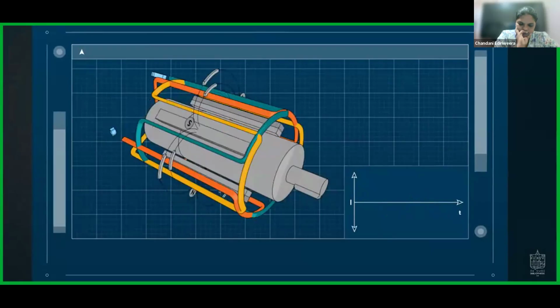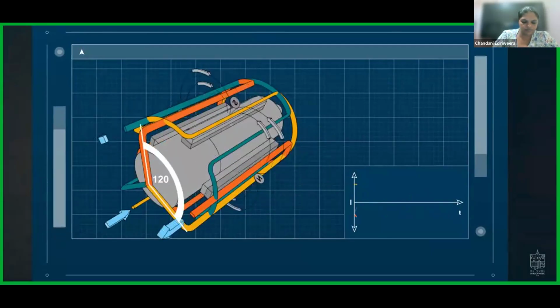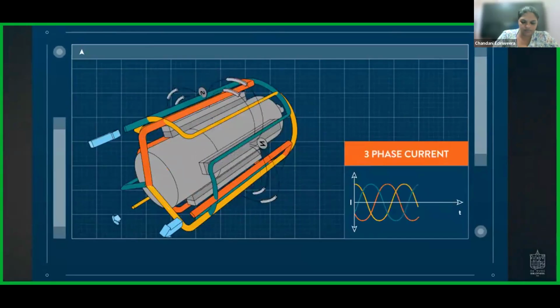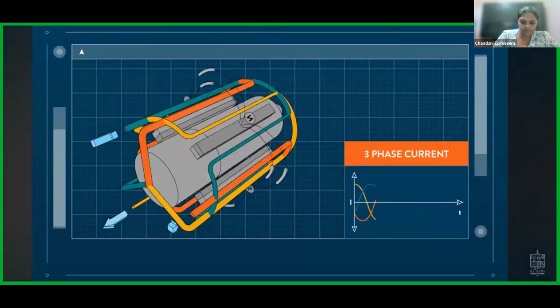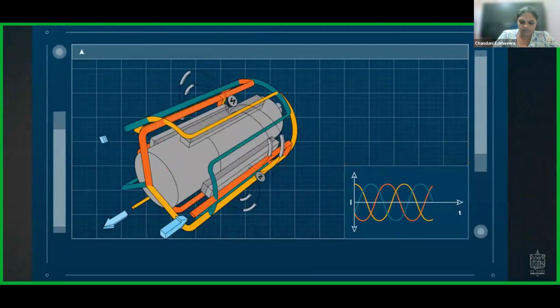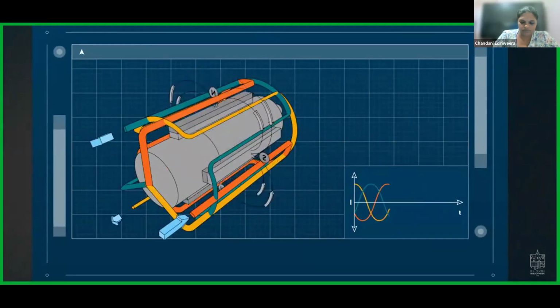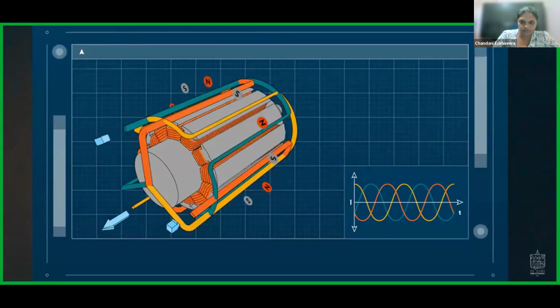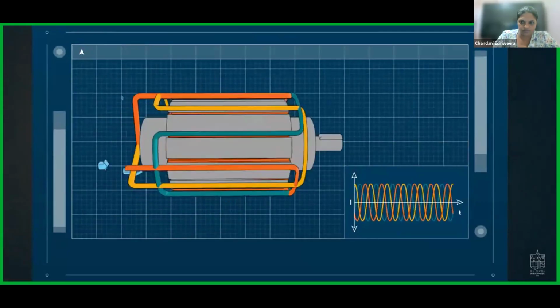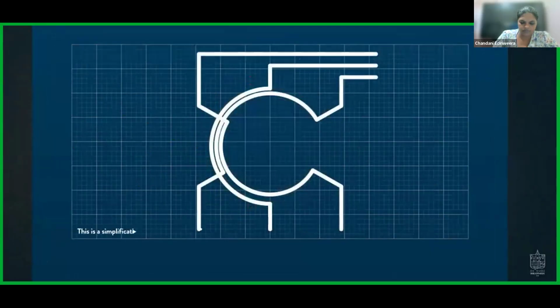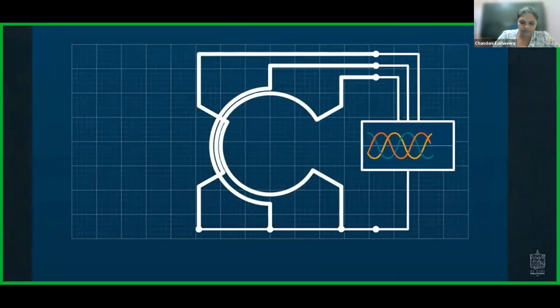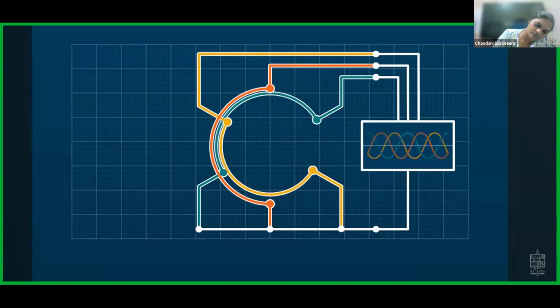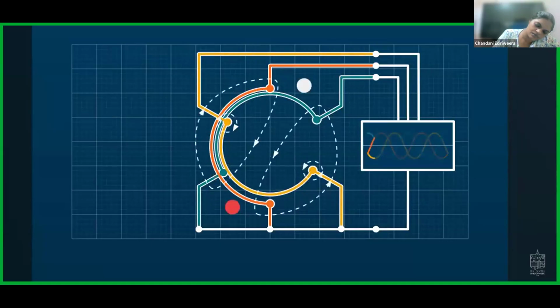By adding 2 more armature coils at a 120-degree angle, a 3-phase current can be generated. This is generally used for transporting electric power. The speed of the alternating magnetic flux defines the frequency of the current. So adding more poles and more RPM creates a higher electric frequency. Now let's consider that the armature coils are connected to the 3-phase current of a grid. This 50 Hz 3-phase alternating current actually creates a rotating magnetic field, like this.